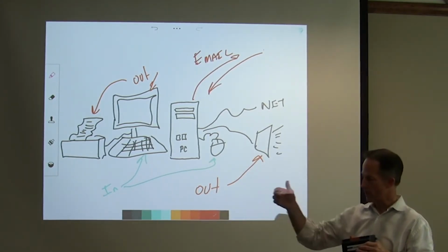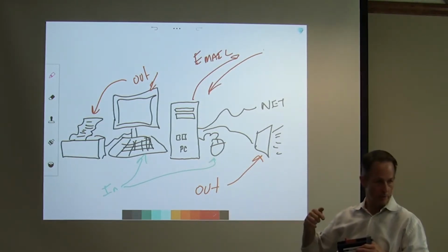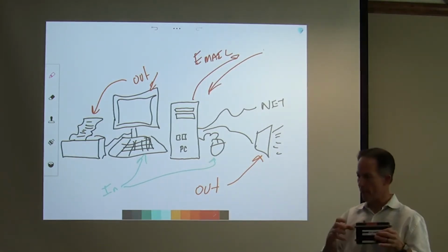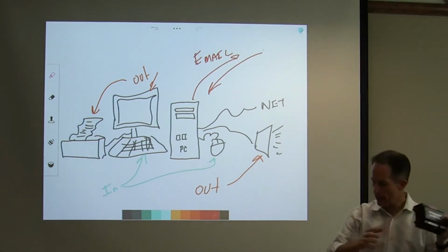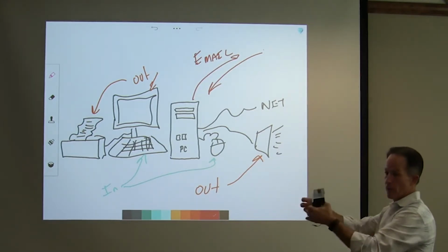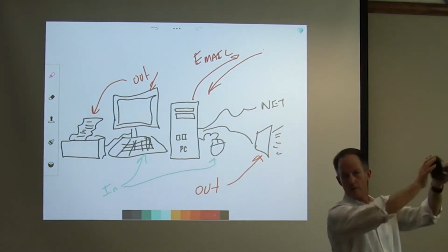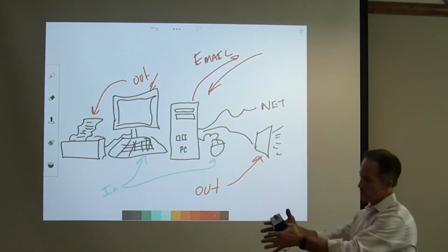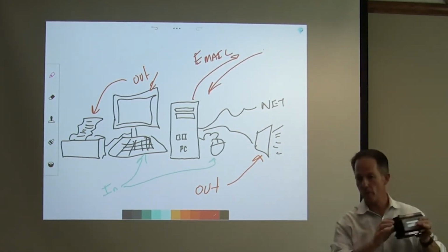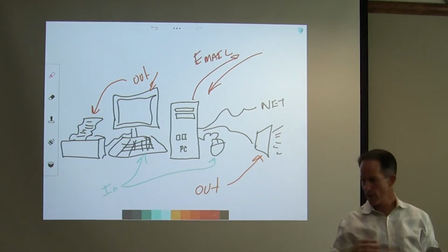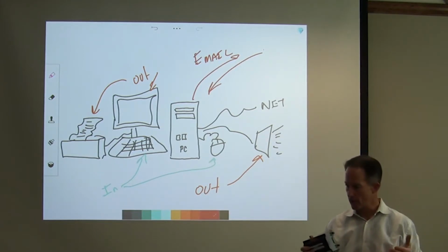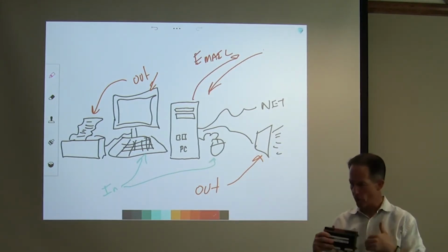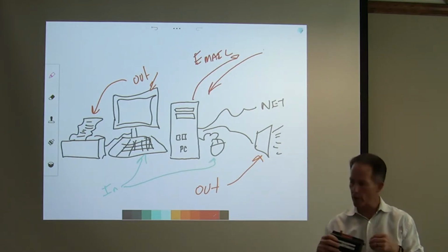So for the controller, that outside air is an input. And then once I have it as a point, the controller turns and says, I'm going to output that to the network. The next Jace says, I'm going to input it from the controller. I'm going to output it to the bigger network. The supervisor says it's an input to me. Then I'm going to output it to the Jaces or other places. So it can be both depending on which way it's coming, and you always take the position of either the controller or the place where you're dealing with that point. Okay.